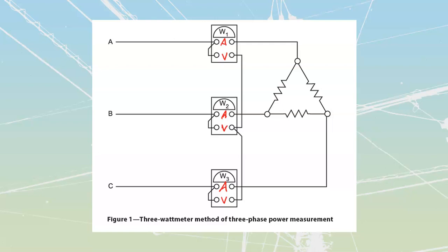When we're doing the 3-watt meter method, we're basically placing an ammeter in each line. It's the same as if we had an ammeter in each line. I'm just drawing them in separately over here. And at the same time, we were also measuring values of voltage inside of each line over here. Sorry, I'm going to draw that as an actual circle here. But if you take a look at the connection that we have, you'll see that the connection is actually a delta type of connection.